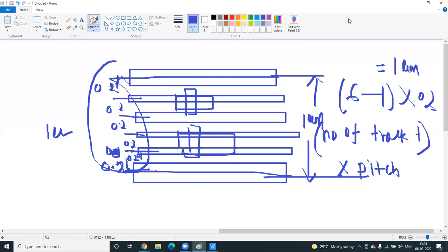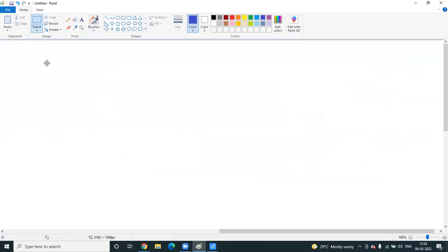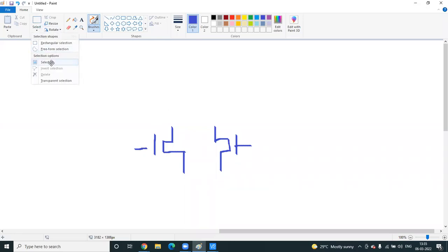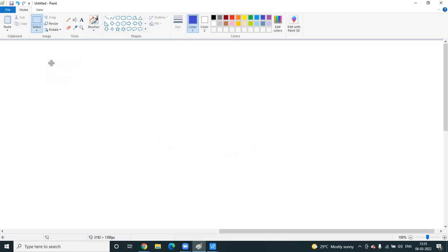So I have one doubt. In the op amp, we are using the current mirror, right? For that, I believe we are using common centroid matching. Why not? No, not for current mirror. Sorry, the diff pair uses common centroid matching. For the current mirror, generally sometimes we use interdigitization or no matching. No matching means normal matching.